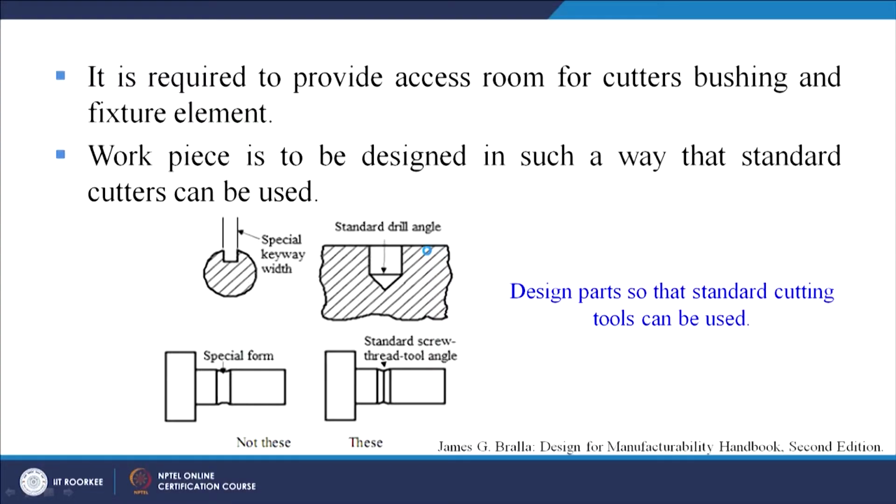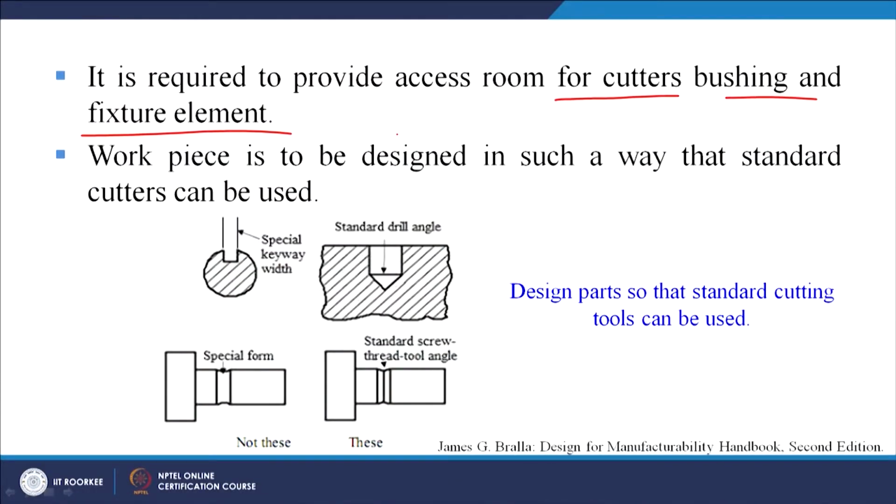So it is required to provide excess room for cutters, bushing and the fixture element. We must try to design the part in such a way that the cutters, bushing and fixture element have access to the section or the part of the product. The workpiece is to be designed in such a way that standard cutters can be used. Design of the cutting tool is again a challenging task.